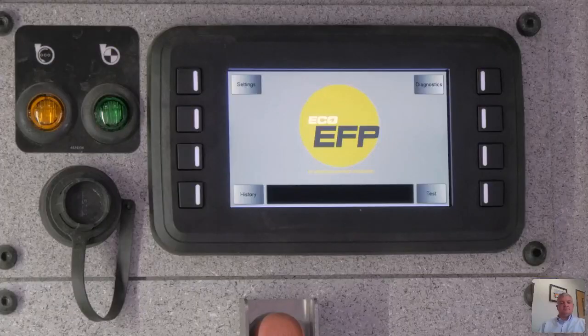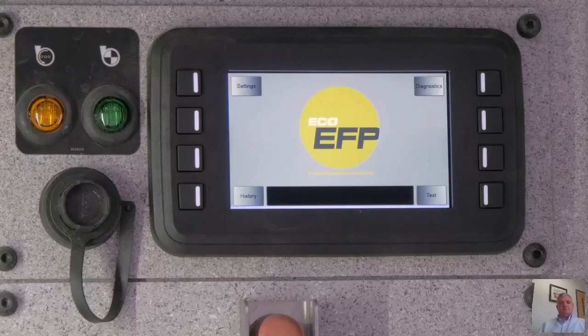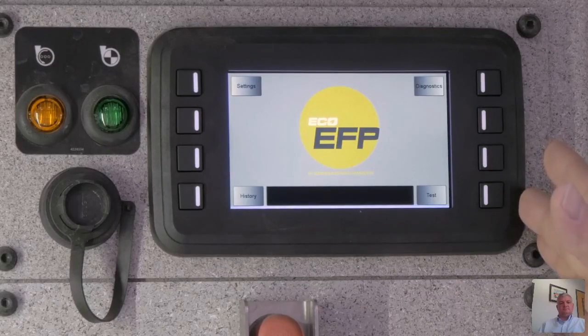The Oshkosh Eco EFP system is both easy to use and versatile. The user interface allows the operator to go through a step-by-step process to do the foam test. All the data is recorded within the vehicle, and the operator does not need to hook up anything to the vehicle, do any setup time, do timing, or any calculations to figure out the foam percentage. The center of the Oshkosh Eco EFP system is the test screen that is located on the structural panel of the truck. This is where the operator selects what tests they would like to run. This user screen will lead the operator through the test screen by screen and allow them to run a test without putting foam on the ground.